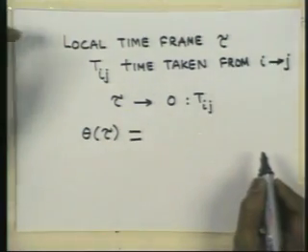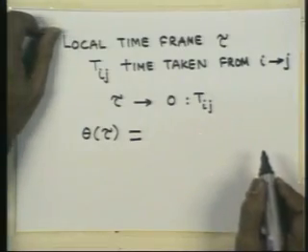Now, what would be the trajectory that I would get? I need to plan for this. So, we could think in terms of a polynomial variation of theta with respect to time within this ij, and the degree of the polynomial could be determined based on the number of constraints that you are placing.